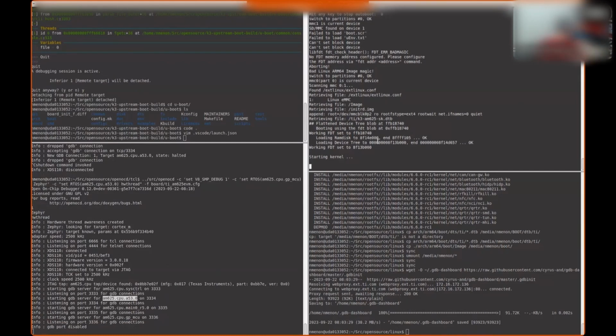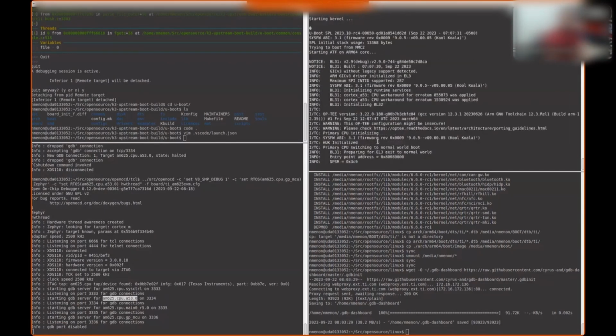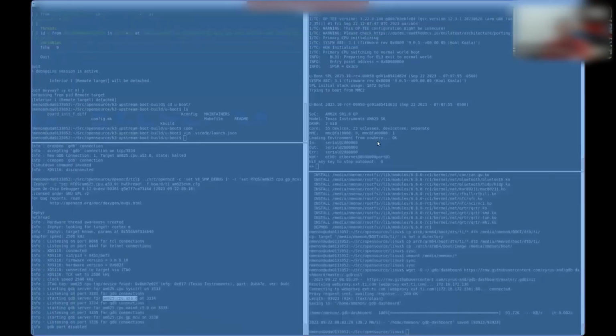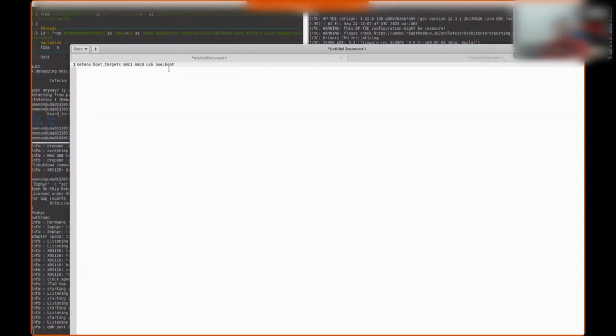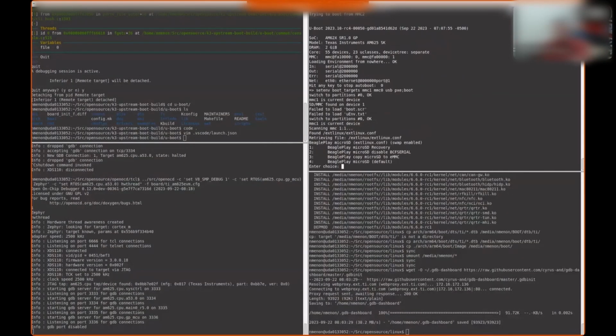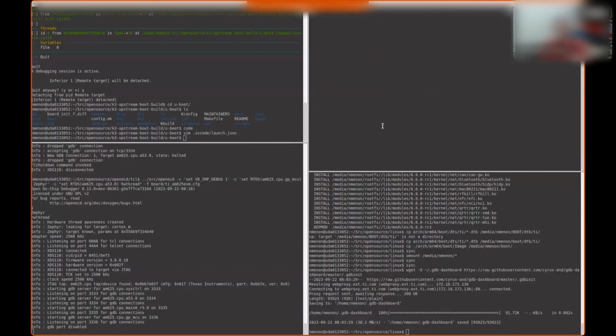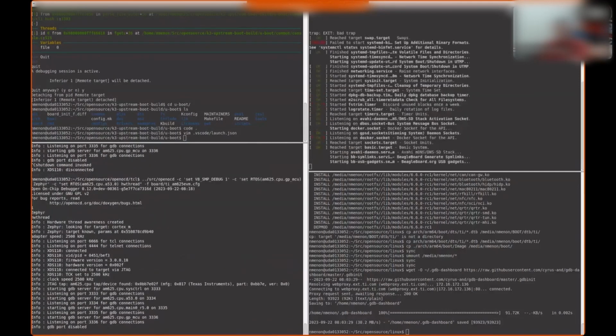Now, give me one second while I work around a little bug in our system. Right, that's my editor. So upstream U-Boot tries to boot out of eMMC all the time, which is not what I wanted to do. Select 4. So the kernel is starting to boot up. Okay, it's doing its user space stuff, and OpenOCD is ready to go here.